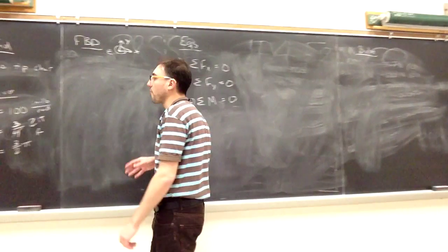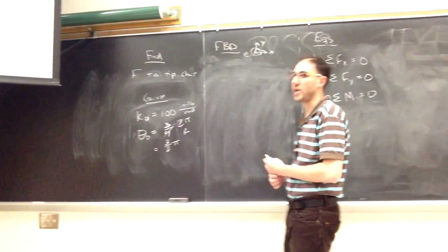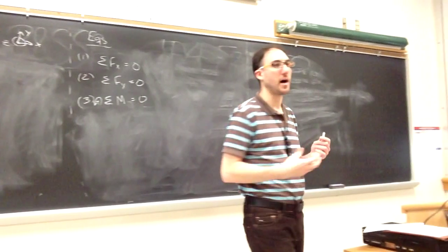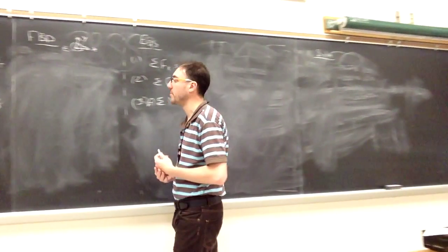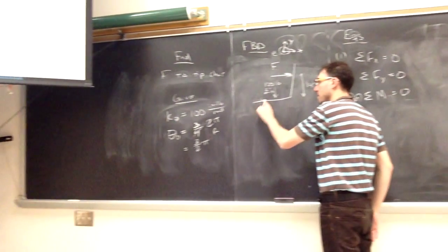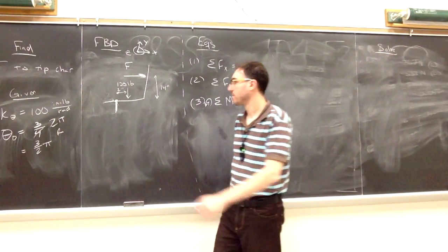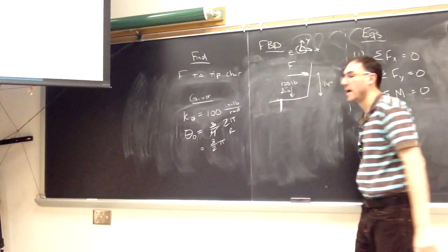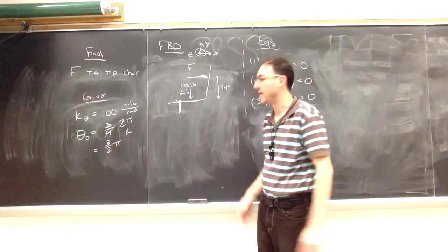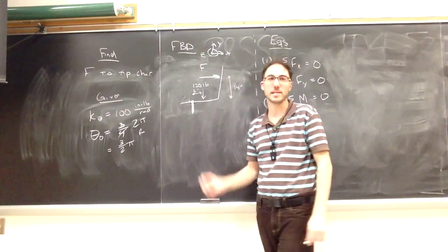We'll head to the free body diagram so we can find the force required to start to tip the chair. What will the object be for our free body diagram, where we isolate it from the rest of what it's connected to? I do want to include the post in my free body diagram as part of it. So as my object, I actually want the seat and the post. You'll see why in a minute this is going to help. Beforehand it's not the most obvious thing to do, but we'll see later in the equation step that including the post rather than separating it will help us.